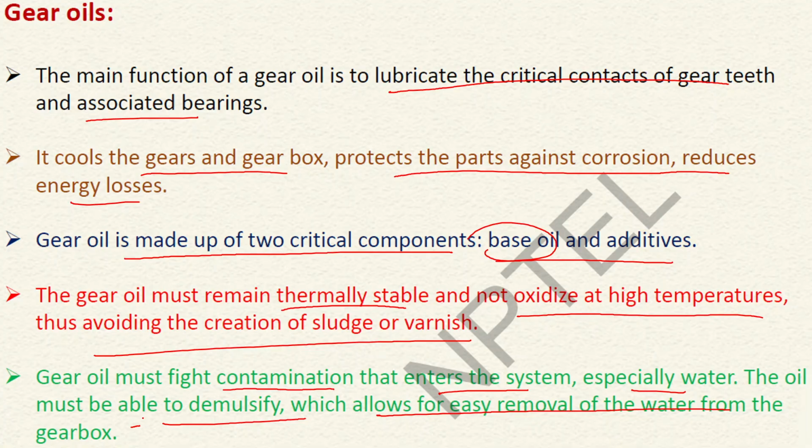So some demulsifier agents are also used so that if some amount of water enters into the gear system, then this gear oil also easily demulsifies and removes this water which has entered into the gearbox.